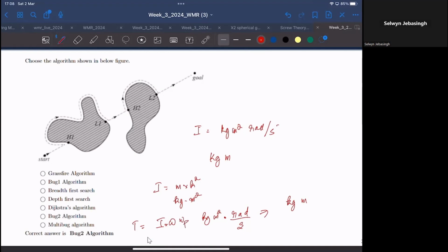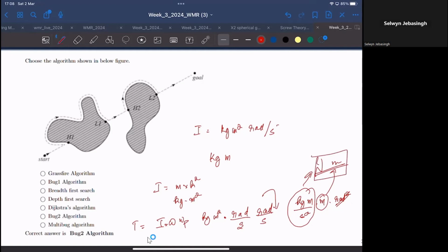There is also one more omega p, right? Yes, sir. So again, one more radian per second will be there. If you rewrite this, it'll be kilogram meter per second square. Then you also have one more meter here. Then you also have a rad square, which does not have any unit. So this kilogram meter per second square itself is Newton, right? And the remaining is 1 meter actually. So units are automatically taken into account, okay, sir. That is how you get Newton meters, because everything is already there. You don't have to convert it or anything like that.